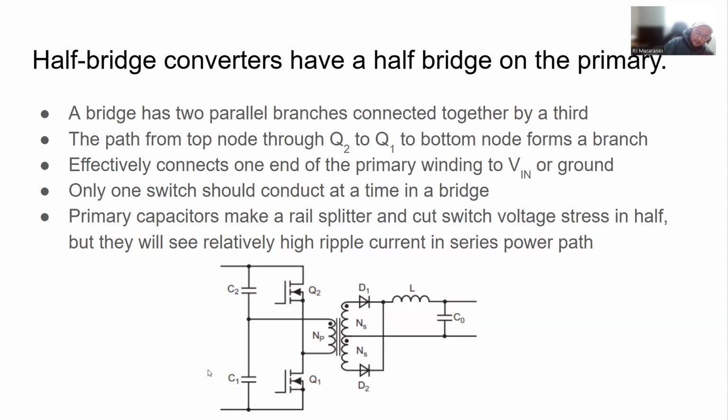To give you some context, we haven't really talked about this all too much, but capacitors have some amount of resistance. And if you have current with a relatively high RMS value, then you're going to have significant power being dissipated in those capacitors. And then those capacitors will break down just like anything else that has high enough power, enough to melt the part a little bit, right?